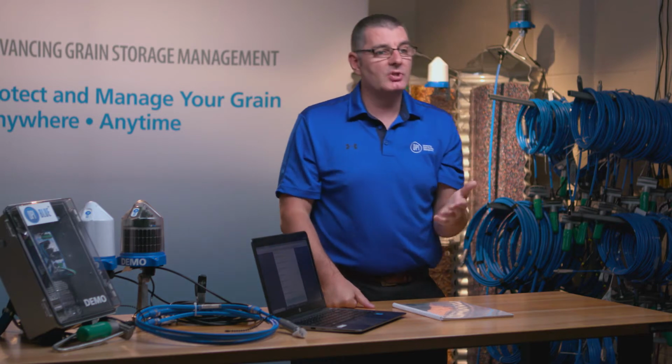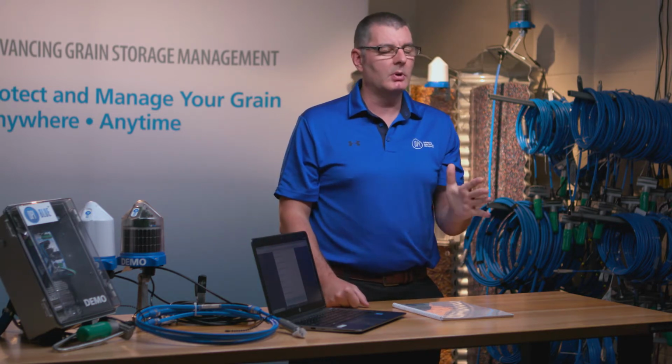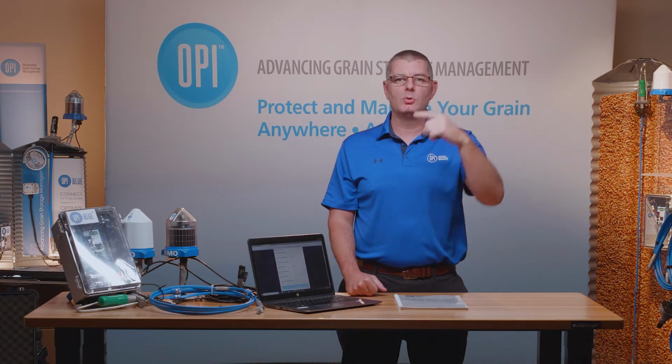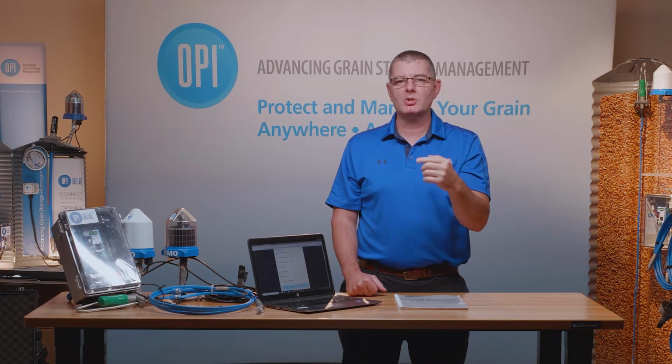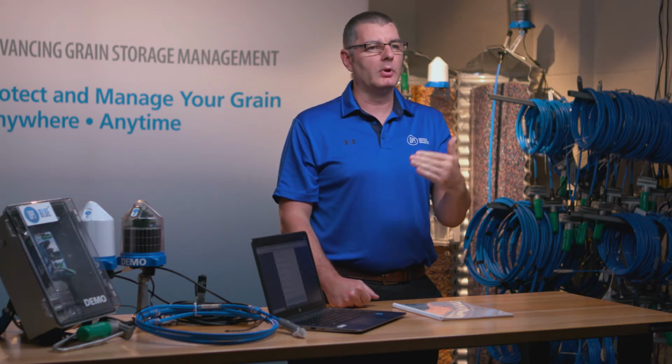The default is 300 seconds, so 5 minutes in this particular case, but it's user configurable. You can set it to whatever you want. The reason that's important, and the same thing with the minimum fan off time, is if our operating window or our conditions to operate or turn the fans off are right on that cusp of either the high or low end to where they're in or just out of the targets, you don't want your fans turning off and on, cycling off and on over and over.